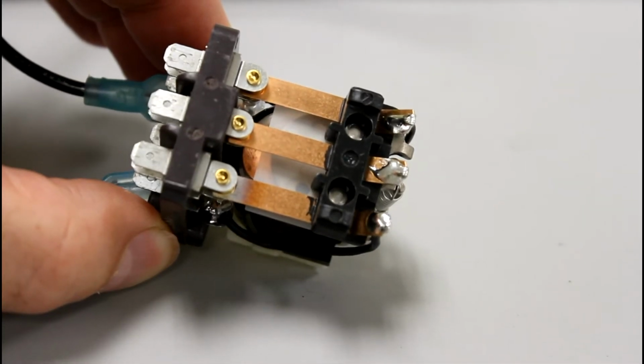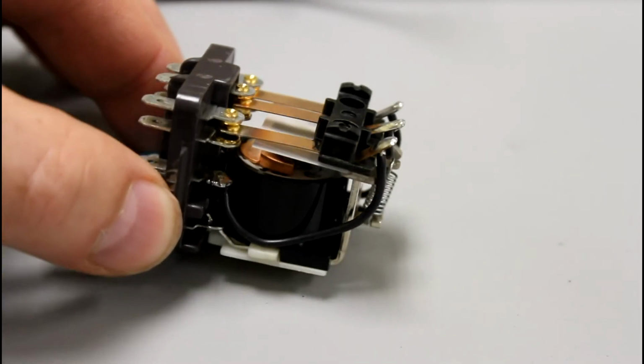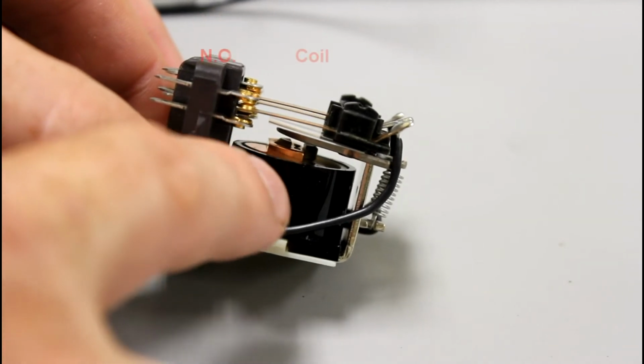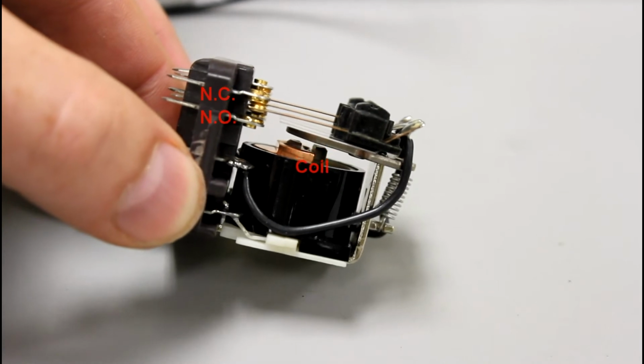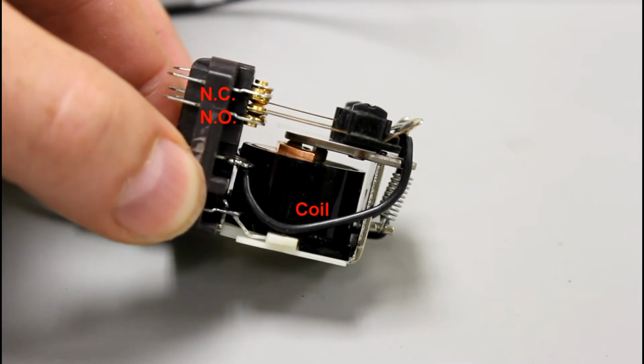Here we see a 3-pole relay. It's a double throw on each one of them. If we look right here, we can see the coil. When I energize the coil, you'll see the contacts move to the down position.